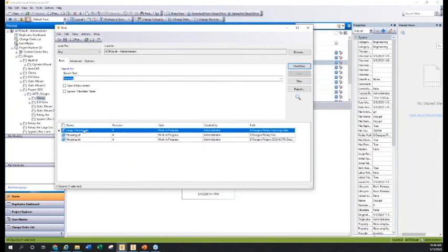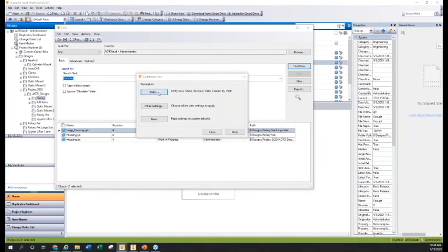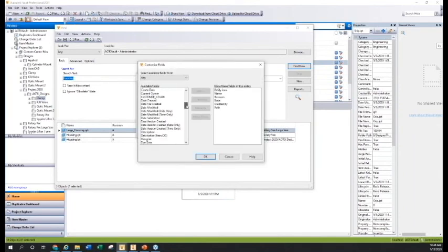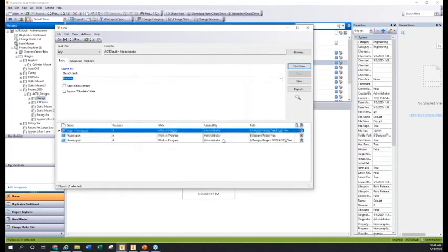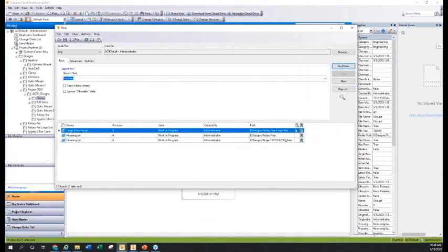We see the path, but if I want to see which one of these actually has parents and what the parents are, we can add that other property in here. So if I go customize view, let's go to the fields here, and that should be in, scroll down. So remember I talked about the has drawing, that's a nice one. I'll put that one in there too, has drawing, and then has parent relationship, put those in, hit OK. And you can see it's just an indicator there. So it's the drawing, you can see none of these have drawings currently, but all three of them have parents.